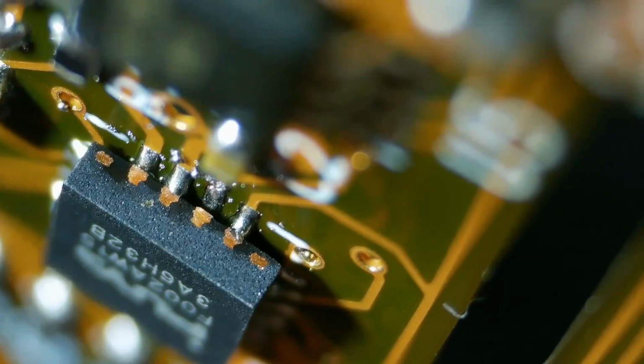I also had some solder bridges on the op-amp that needed correcting, and one of the parts was in backwards, which was probably due to my laziness with the silkscreen. I reworked this by hand off camera. I'd like to put out a video at some point on some of the more advanced soldering techniques, some that you can do cheaply and effectively in the home shop, and we'll cover all of this in more detail.